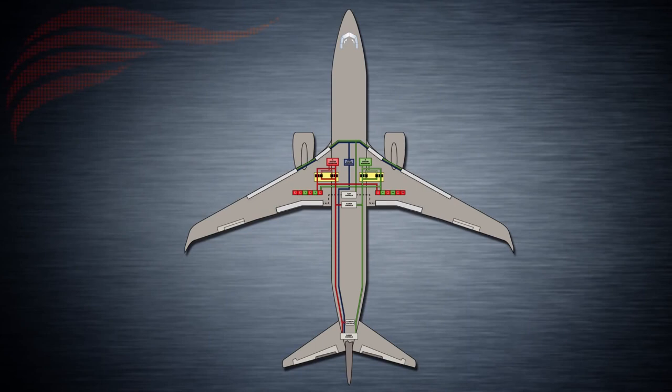When the flap lever is moved to any other detent after 5, the trailing edge flaps move to their respective position. Along with this, the leading edge slats extend completely. The leading edge flaps are already fully extended.